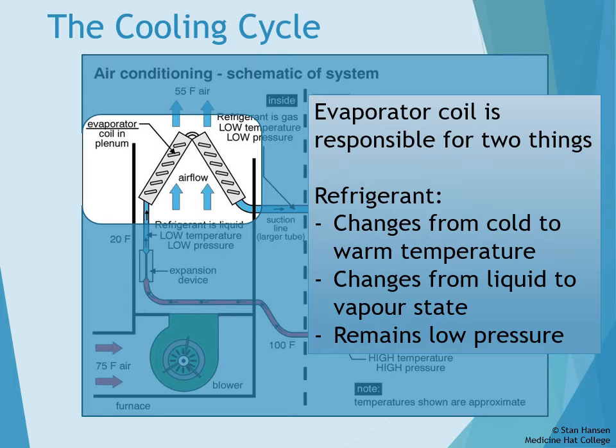Lastly, the refrigerant goes into the evaporator coil. This is placed in the upper air plenum of the furnace, and the furnace fan is interlocked with the air conditioning unit to circulate the house air through the evaporator coil. The cold liquid refrigerant from the expansion valve enters the evaporator coil, and since the refrigerant is so much colder, it pulls a lot of heat from the surrounding air.